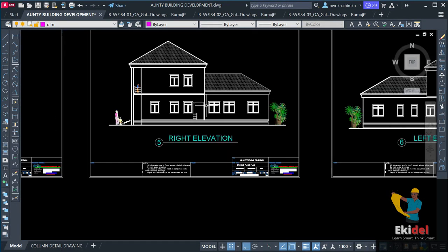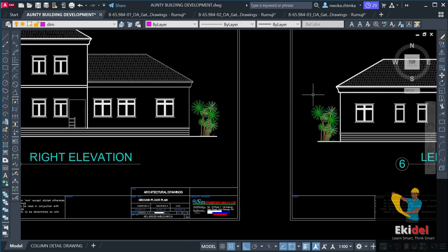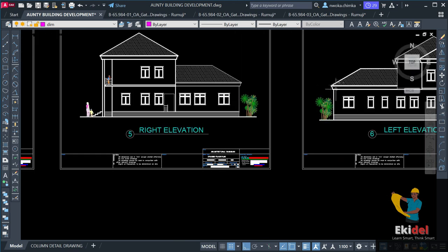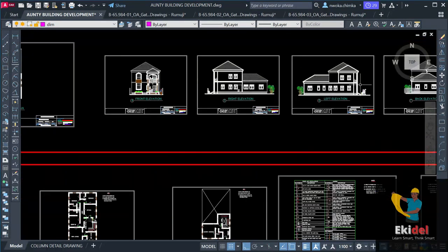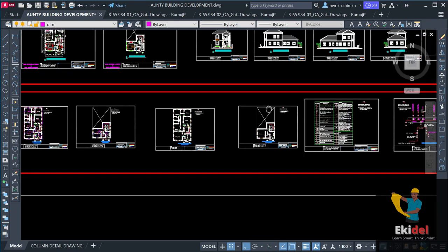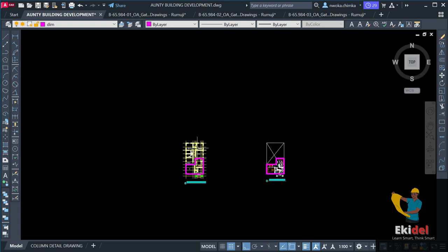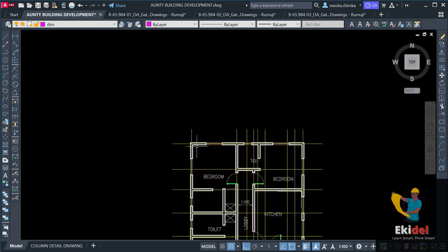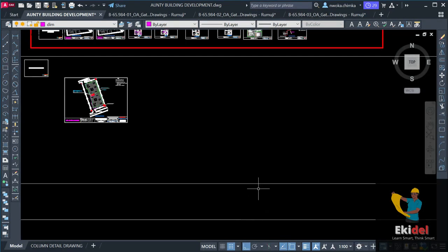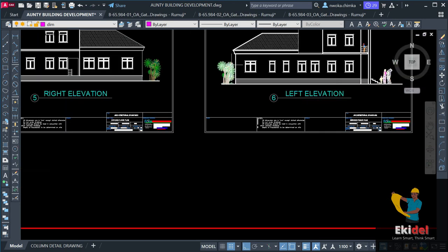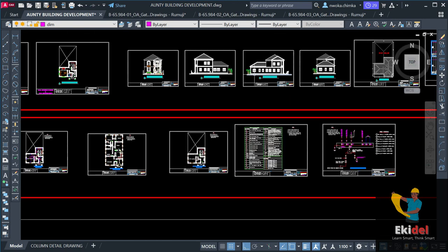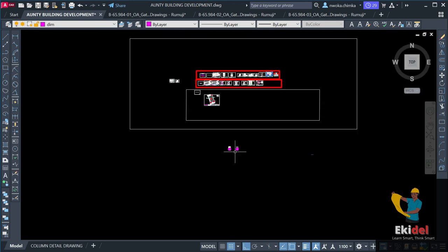And when you have parapets on the edges of a building, it's advisable to put a column at all the edges having parapets, because parapet loads are being transferred or carried by the column. Also, I always advise you put a column. So since this building right now has a parapet at this point, as you can see here, I'll put columns at the edges of this building.